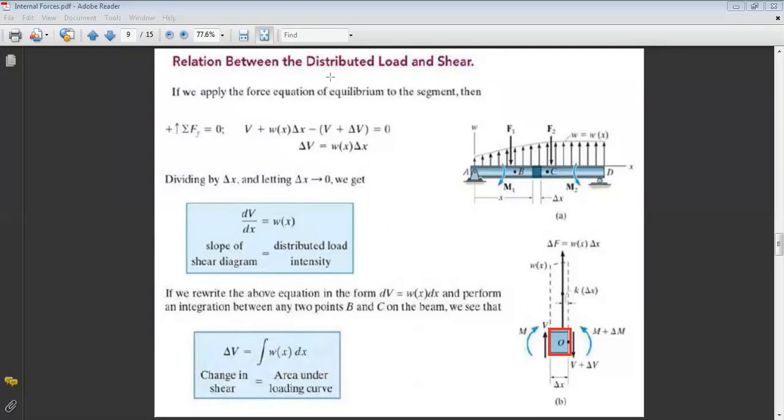Now what are my internal forces? Since I did a cut from two sides, from the first side, the convention is to have V in a way to rotate about the other extremity. So V should be upward. And for the moment, the convention is that it should compress the upper part. So the couple moment will be like this. From this side, I will call the force at this level shear V, and I will call the moment M.